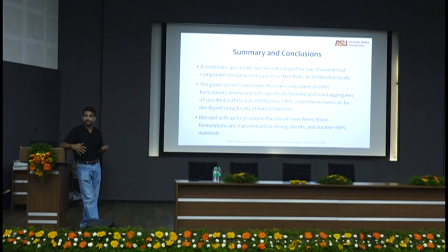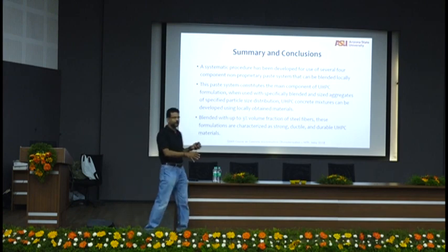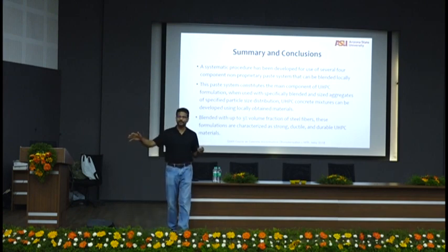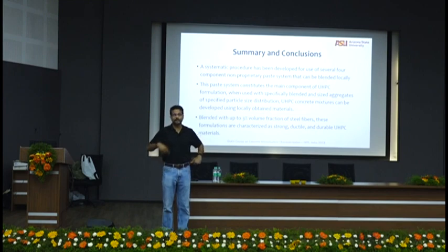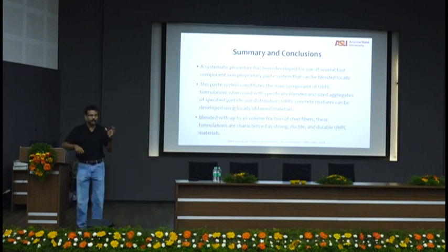The only thing is the mixing time is much longer. This concrete, from the addition of aggregates all the way to the final mix, takes about 25-30 minutes of mixing with very high admixture quantity. That's something they had to be trained on, and the addition of fiber. So we carefully organized what raw material will be added at what time, sequenced all of them, and gave them a sequence chart and a test procedure.